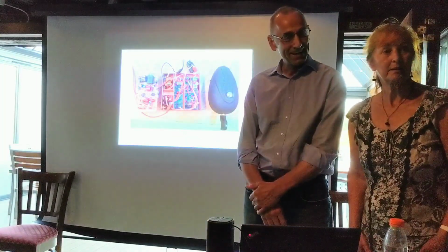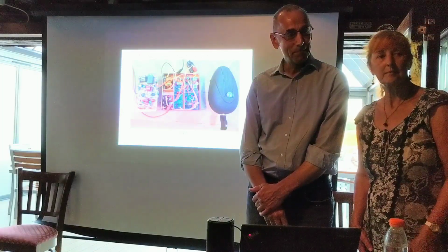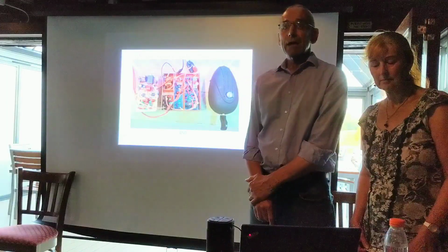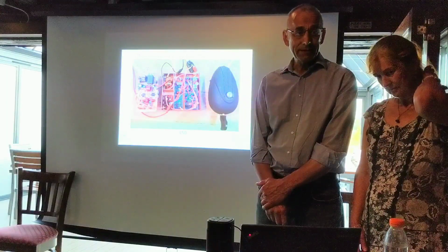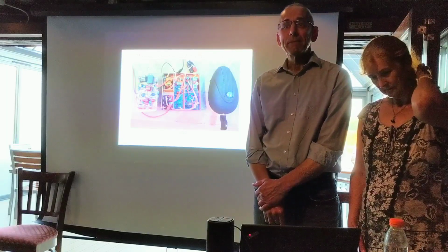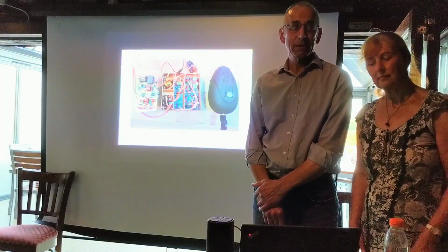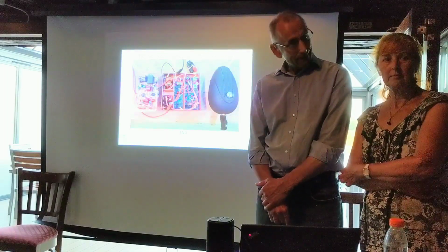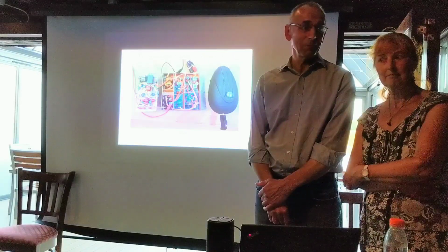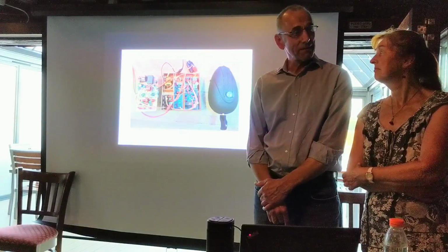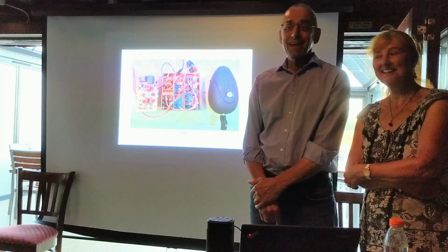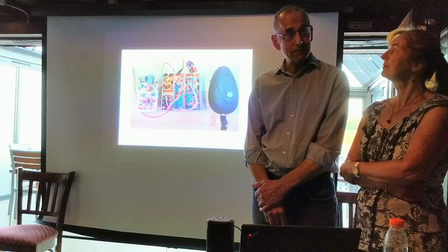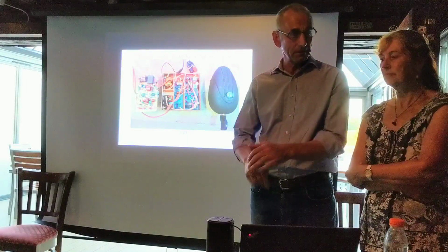The double balance mixer you're using, why did you go for that? What's the benefit of that over a passive component? It has the amplification. It has 20 dBs of gain at the front end, which is great. In the converter I made for SAQ, it's got all the oscillator circuitry in there, so it's very simple to use. And I had them in the junk box. I bought 10 of them on eBay, so I had 9 left over. And it's got relatively few components. If I'd used the diode thing, I would have had to make 2 matching transformers and carefully wound them so that they were all balanced.